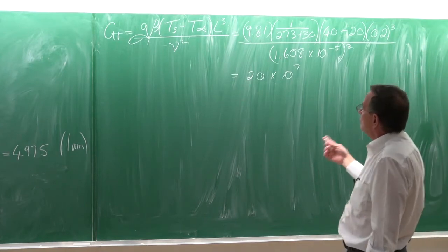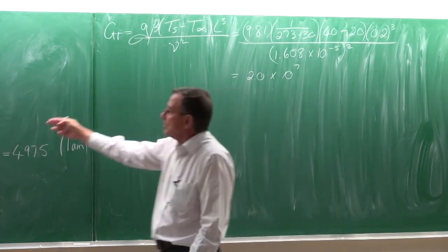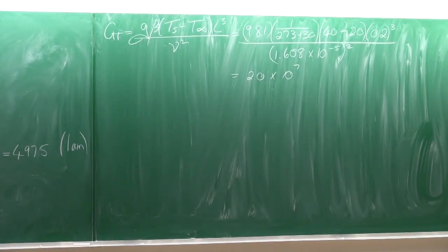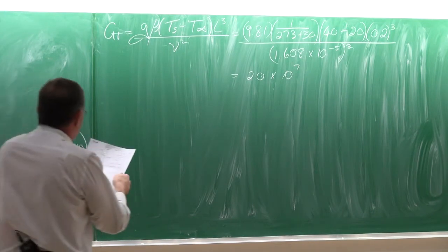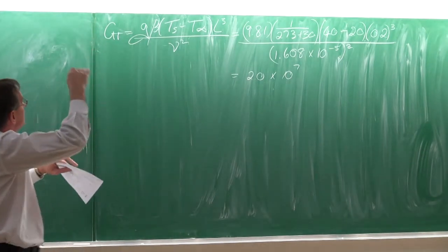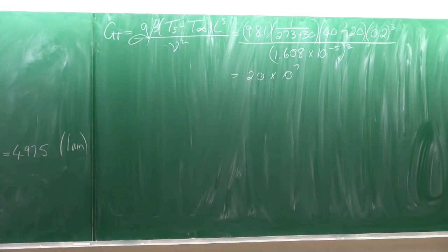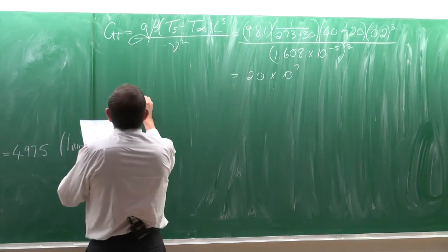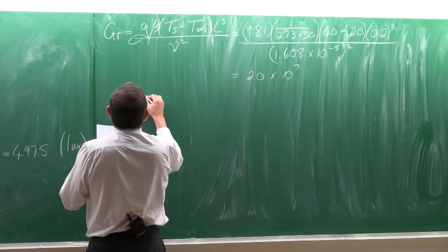The Rayleigh number would be the Grashof number multiplied by the Prandtl number. So you can go and write down the value to determine the Rayleigh number, and then determine which equation should be used. That is what I also did when I selected one of the equations. But before we do that, we need to determine what type of problem it is.